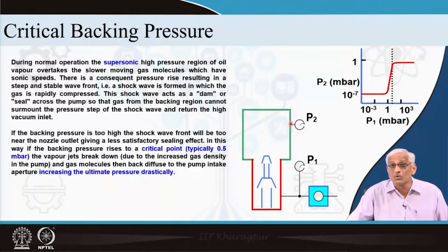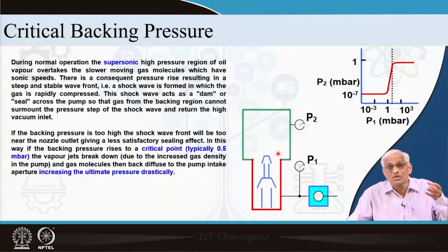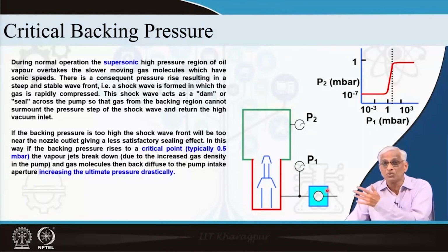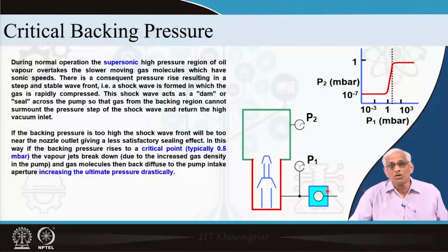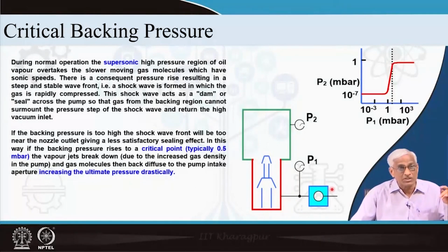In metallurgical furnaces, it is not only evacuating the chamber during melting, or thin film depositions, it will evacuate those extra molecules also. We have to maintain that vacuum level, and certain molecules during the loading conditions also have to be removed. At that time there will be fluctuations here, but the rotary pump should be able to handle them. So, all these things you have to take into account in the vacuum system design.